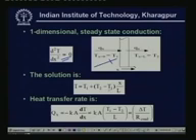That means the temperature variation is typically linear, and the heat transfer rate can be obtained by applying Fourier's law here. Qx is minus kA dT by dx. So the temperature profile is used in this equation, and then you get the expression for Qx in terms of the temperature difference delta T, where delta T is T1 minus T2, and the properties k, the thickness L, and the cross-sectional area A. So this equation can be written in this form, that means Qx can be written as